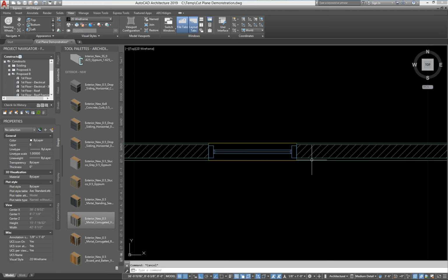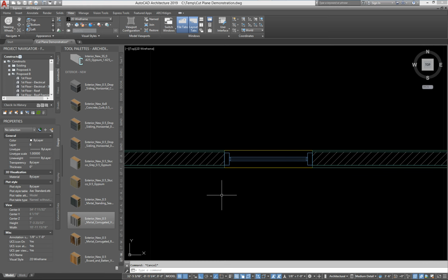I don't see that window. Often, if I have this type of a gable end scenario, I want to have the window display because I'm going to tag it, and I also want the contractor to understand that I either have an existing case of a clear story, or it might be a vent or just a decorative window, but I want that shown in my 2D plan view. So what can we do? Well, the first place to start is with the object itself.